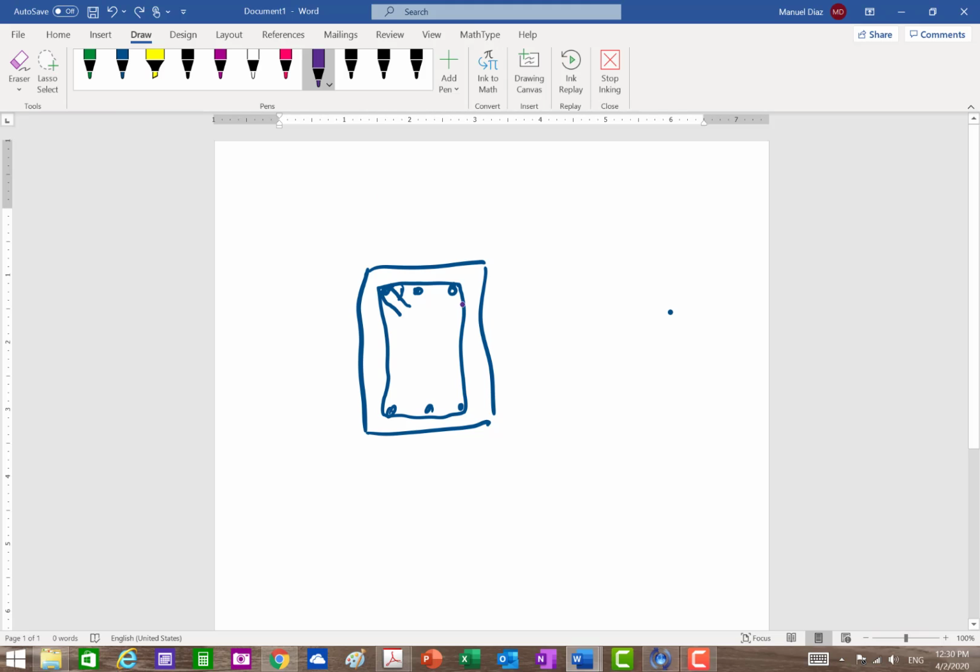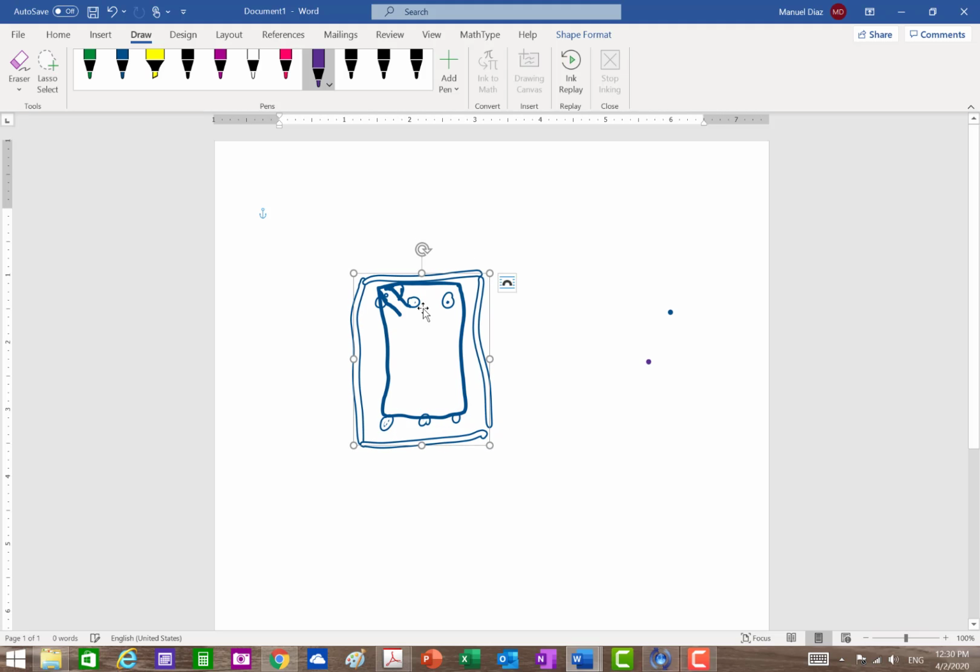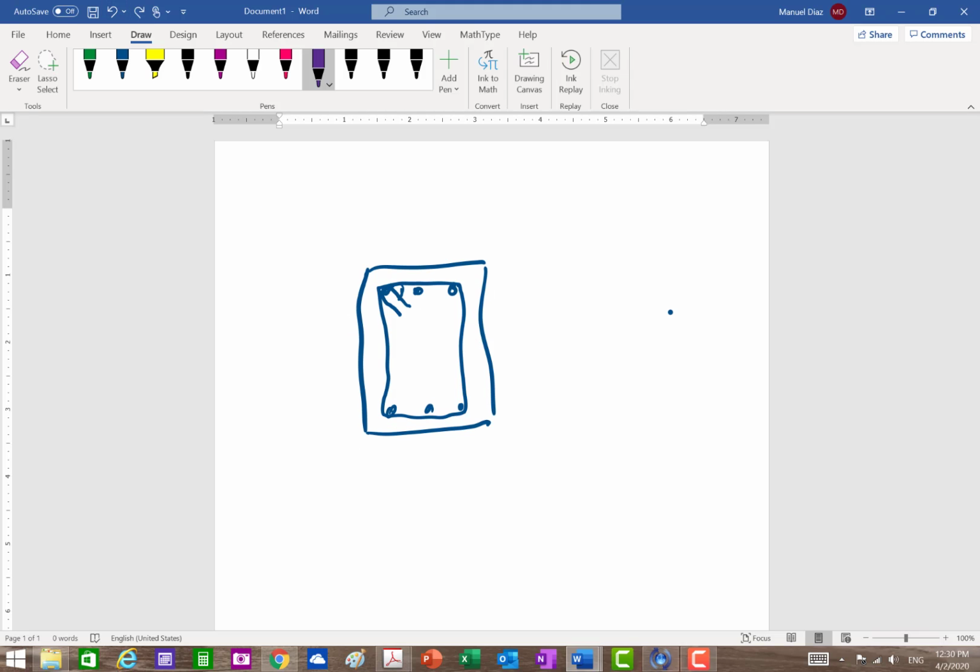Then this says also that you have to cover the corners, and you could skip 1 bar. That's all you can skip, as long as the clear distance is no more than 6 inches.